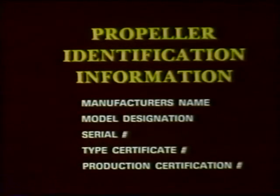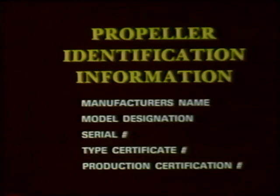Aircraft propellers must be certificated under FAR Part 35 and must contain the following information on the hub or butt of the propeller blades: manufacturer's name, model designation, serial number, type certificate number, and production certificate number.